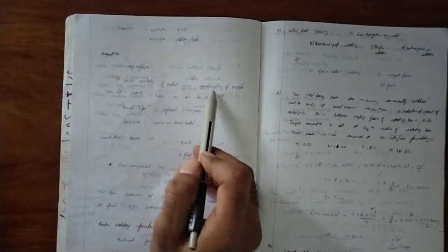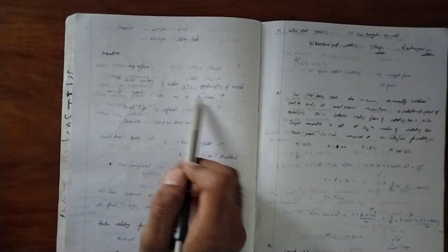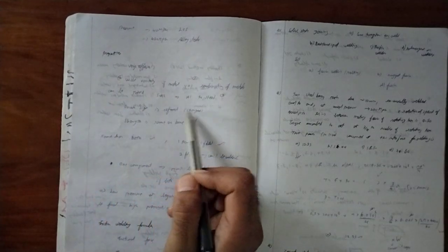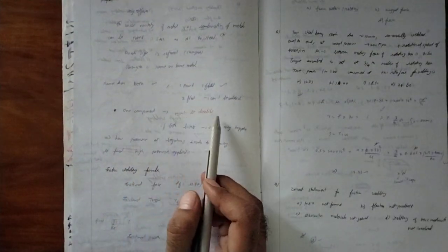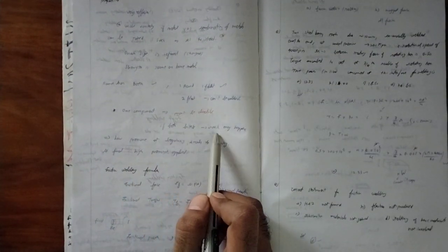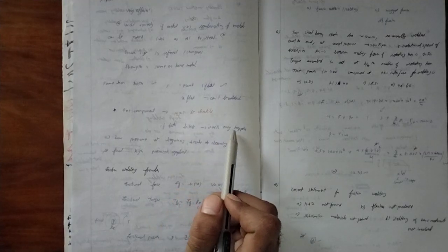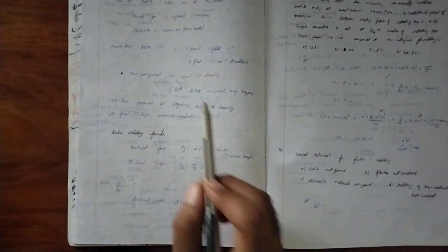Power is about this much, and axial pressure depends on the strength and hardness of the material to be joined. You can see a wide variety of metal combinations can be used, such as aluminum to steel, and the grain size is refined, and strength is better than the base metal. Generally one round and one flat, or two flat pieces can be welded. One component must be ductile and the other brittle, because if both are brittle, cracks may appear and lead to breaking. That's why we use it like this.